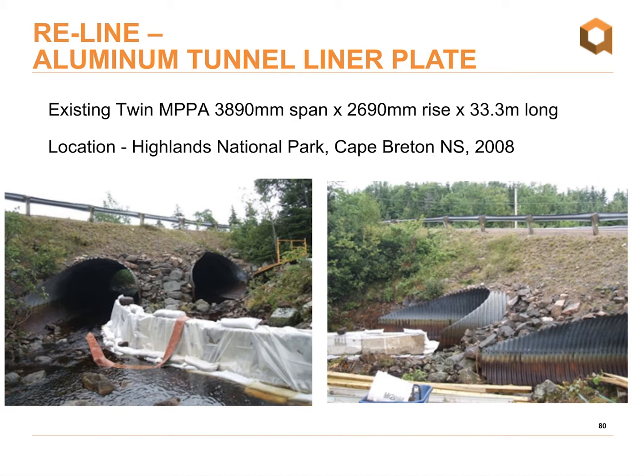Back to Nova Scotia again. Here we have twin multi-plate pipe arches in Cape Breton Highlands National Park. They're 3890 millimeter span, 2690 millimeter rise, and 33.3 meters long. For this reline application, again, aluminum tunnel liner plate was chosen. Given this was a twin installation, the contractor was actually able to set up a cofferdam and completely divert the river through one structure while the other one was being worked on in the dry.